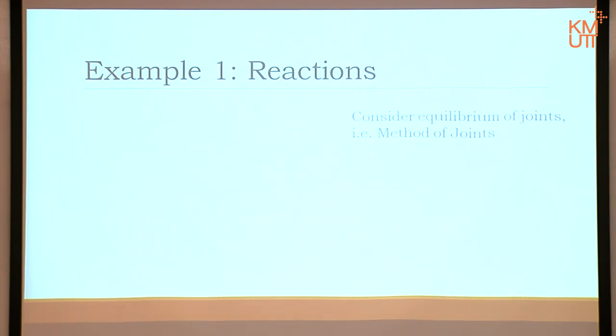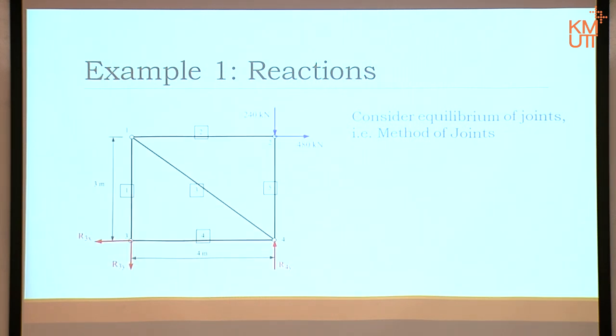Usually if they ask you to calculate all the internal forces and the picture is not so big, generally you can guess that it's going to go by joint method, okay, analysis of the joint. Still internal force. In this case we need reactions, right? Normally, you have a pin support on point 3, 2 reactions, and a roller support on point 4, 1 reaction.